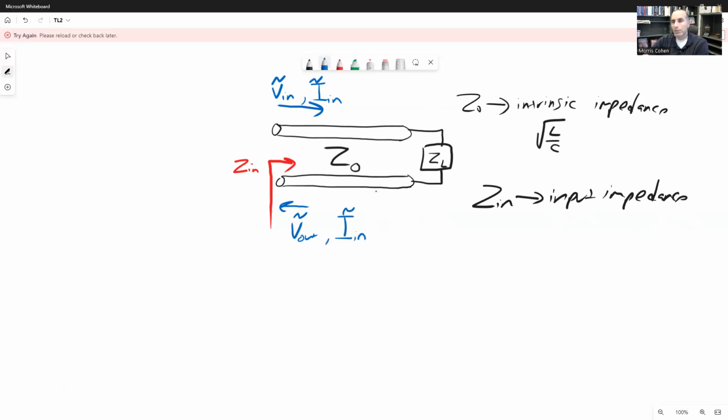All right. Now, what's different about an AC transmission line is that we have a defined relationship between V in and V out. Because if we know this distance, then we assume it has a distance d, then we know what the phase shift of this sinusoidal wave is going to be from this original point propagating down to the load, right?